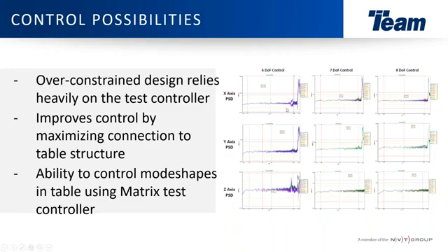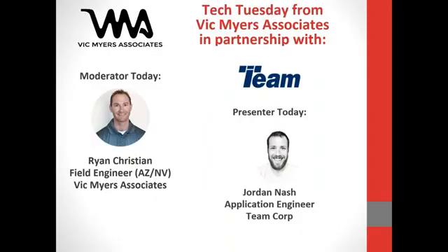Again, the 7 degree of freedom was designed to control that first table mode shape. And then the 8-DOF control was designed to control out as best we can the second primary mode shape that was within the table frequency band. And you can see that with each level of additional control, the 7th and 8th, we've reduced that resonance by some amount, presenting a much more overall control of your table. With that, that's most all we had presented today.